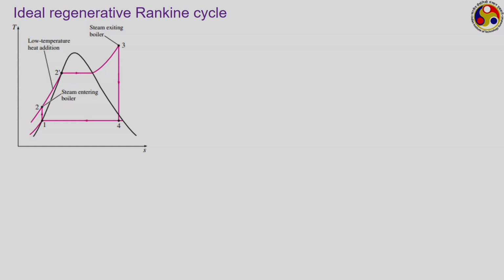Here, as you can see, this is an ideal Rankine cycle without any reheating. Here the boiler operation starts from this state point 2 and finishes at this point number 3. So, this is your temperature T2 and this is your temperature T3. So, the boiler heat addition progresses over a very large temperature range from T2 to T3. There are several example problems we have already solved. You can check out any of the example problems from there.